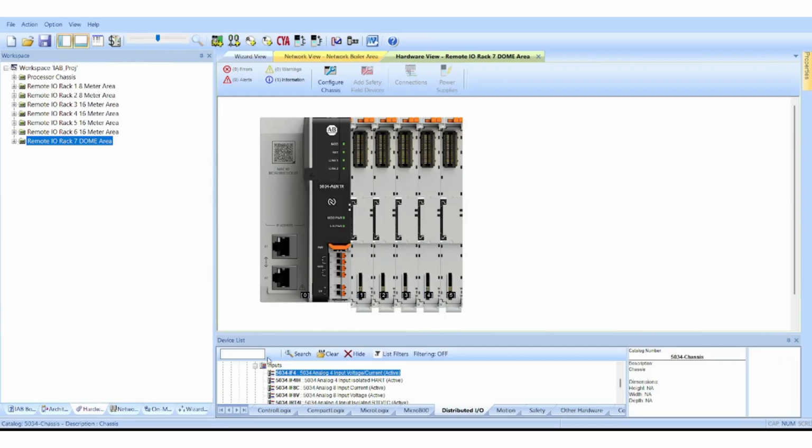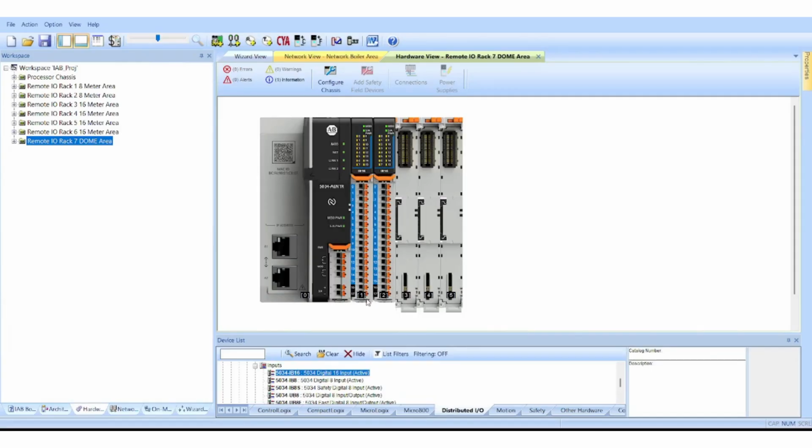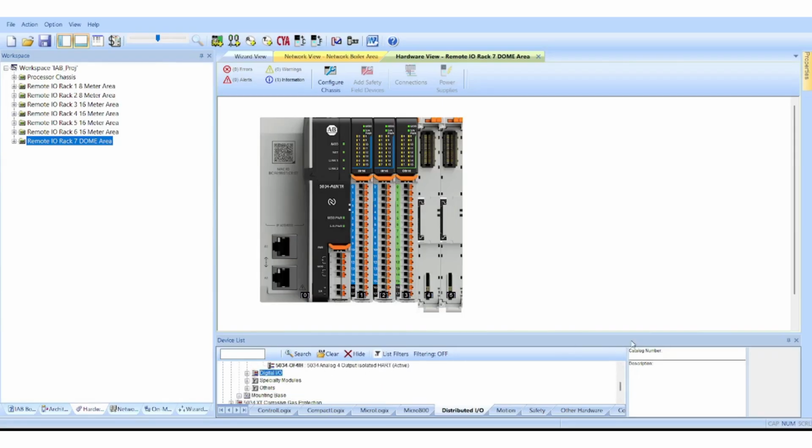During detailed engineering and commissioning, additional instruments, interlocks, or field signals may be identified. If every channel is already occupied, even a small modification can create unnecessary hardware changes. At the same time, excessive spare capacity increases project cost. So the objective is to provide reasonable engineering margin without unnecessarily oversizing the system.